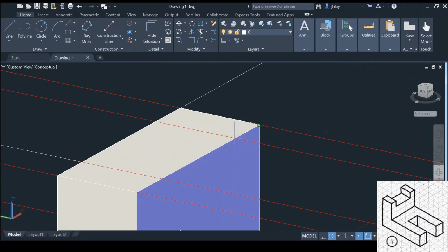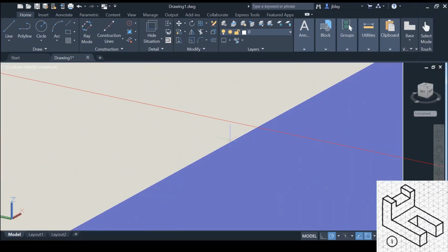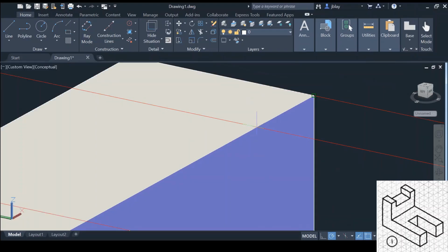And here. And if you have any trouble, it's probably because you're drawing on the wrong plane. So if you ever have an issue, just stop. Restart. I got to zoom in a little bit here. It's not snapping in place really nicely. It's trying to go to the end. So let me actually just draw lines. I think it'll be a little bit faster for me. For some reason it's trying to snap to this end, which is okay. This kind of thing can happen sometimes because there's no line going along this edge. So we'll just draw some more construction lines so we have more intersection points to work off of.